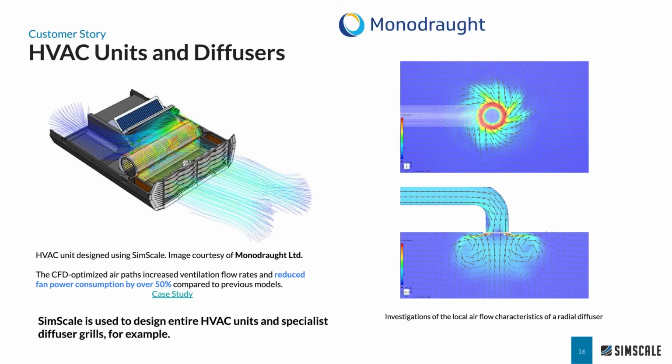Another good example of use of SimScale from customers is Monodrone. So they're designing complete HVAC units, as we can see on the example here on the left side. And they used CFD particularly to optimize the air paths inside the unit. And with that, they could increase the ventilation flow rates through the HVAC unit, but also they could reduce the fan power consumption by over 50%. And this really marks a significant reduction in power use of the unit throughout the lifetime.